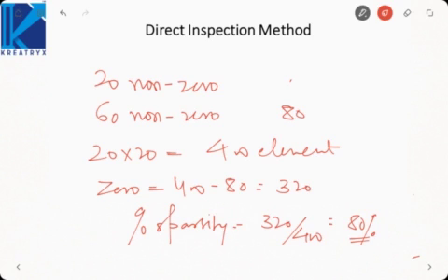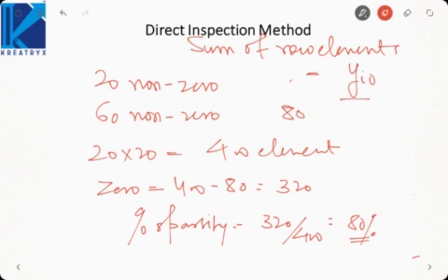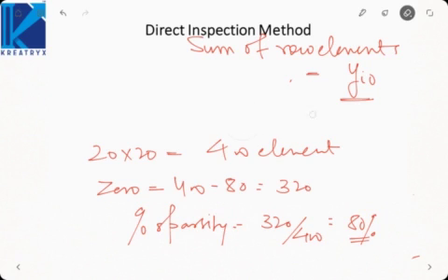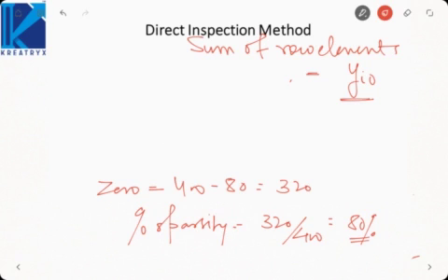Okay, and remember, in Y-bus, if you sum each row, then you will get yi0, that is the admittance between the bus and the ground. Like if you see in the first example that we took, the first row was y10 plus y12, minus y12, 0.